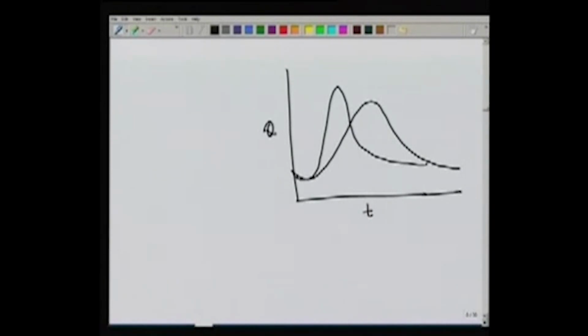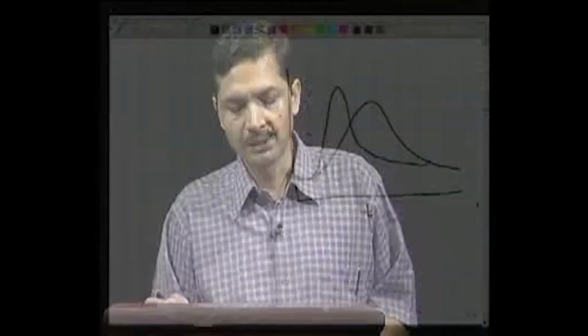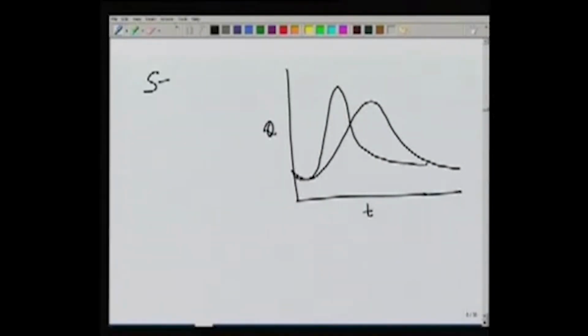So next we will see some of the factors which affect the shape of the hydrograph. We would start with a hydrograph which is of a smaller duration. So it's in response to some precipitation over the area, and then we will go to the higher duration behavior, for example annual hydrograph. The hydrograph which is in response to a storm is typically called storm hydrograph, or simply hydrograph. So in this lecture we will just use hydrograph for the storm hydrographs.